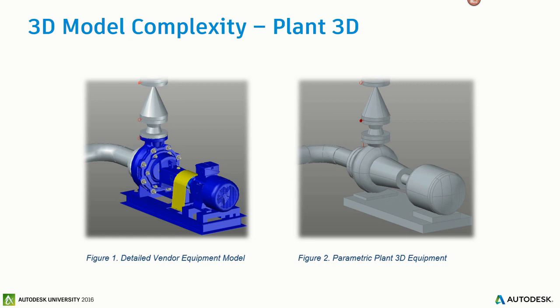I can't tell you how many times I get a call from a customer saying, my performance really stinks, what's the problem? It was working good the other day. And I ask, well, what did you do yesterday? And they say, I put in all these valves and stuff. I start looking at them, and there's name etching on the valves and the bolts, and I'm like, guys, you don't realize what's going on. Just that little bit of taking some of that detail down and simplifying it is going to keep your performance where you want it to be. Because if you get too detailed, you're just going to crash all the time.